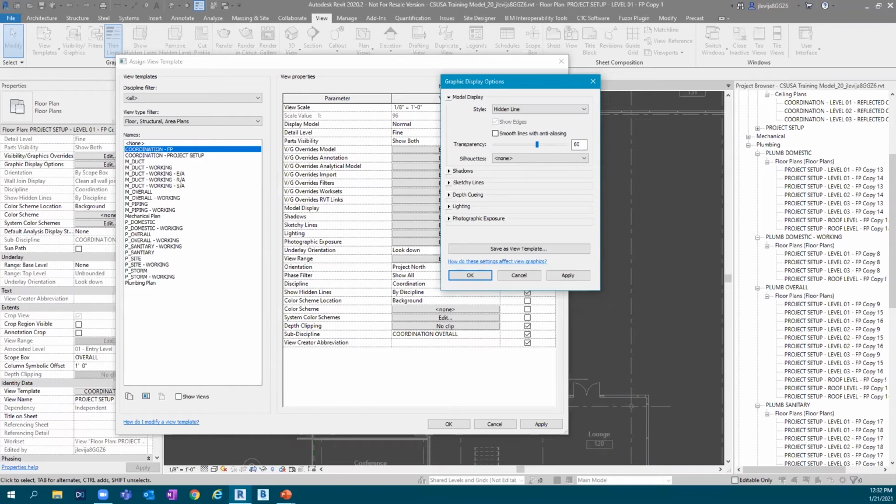And depending on what you guys are producing for plot, in the construction world, when I was working with an EC on the construction side, we would actually plot in color and send that back to our fab department. That gave us a little bit of flexibility when we were separating out systems for conduit, by having that transparency. That way I can see the multiple colors and send that off.